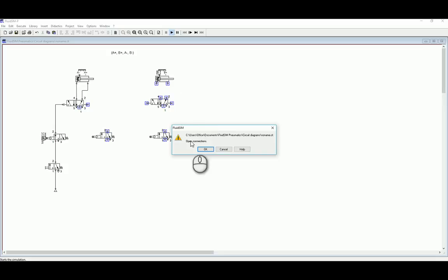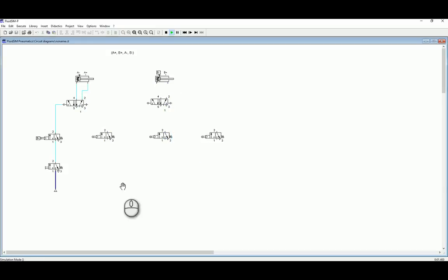So I could test this part of the circuit straight away just to show you. So, yep, a whole pile of open connections, I'll just ignore them, start anyway. And you see the software drops back into a certain position. So as long as B is in the minus position, I'm able to press that particular one, and you see that B minus activates and supplies an air supply into the 5-2 valve. So all I need left to finish off is to activate this particular one to give it an air supply through. And you should see A then extend.